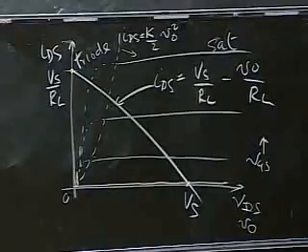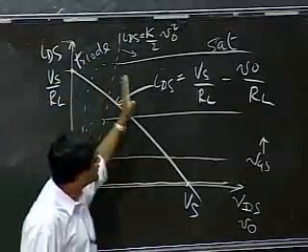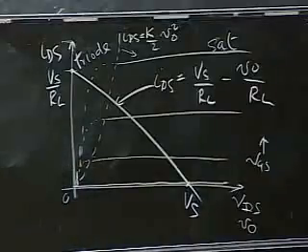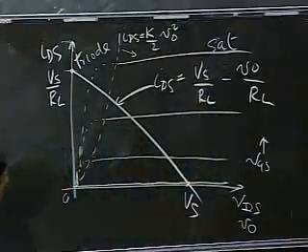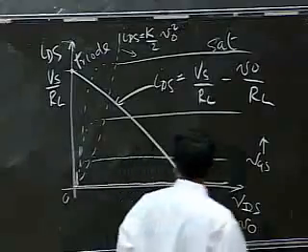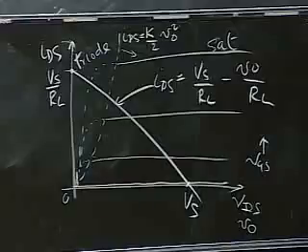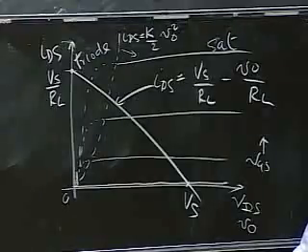So this was another interesting graph. We oftentimes fondly call it the load line graph. So here's a load line superimposed on the MOSFET device IDS versus VDS curves for a variety of values of VGS. By looking at this curve, we can also intuitively determine the valid operating range. Okay, so what are the two points here? I'll let you stare at it for a couple seconds yourselves to figure out what two points bound the valid operating range of the MOSFET, or valid operating range of the circuit.